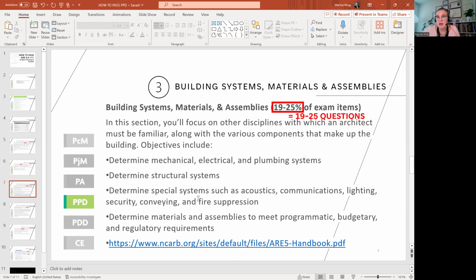You need to plan wisely so that no systems intersect and do not disturb each other. So, for example, your HVAC duct does not penetrate the structural beam, right? So you need to really plan, you need to understand the thickness of the systems and where we place them. How thick is the slab between the floors, and what actually is the general requirement, what ceiling height the owner would like to have, the finished ceiling height.